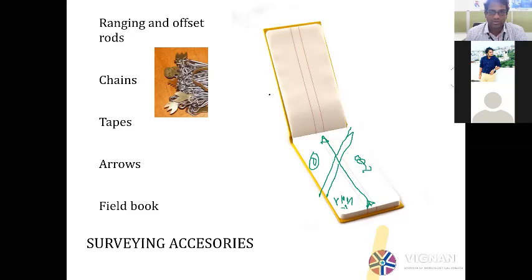That is what I would like to make a point. The chain is always run from here to here. So this end will always be 0. This will be 20 maybe, and this may be again 20, and this may be again 40 meters. I'm talking. So this is the next page. You'll enter 40 meters, 60 and 80. That is how the field notebook is done, right?